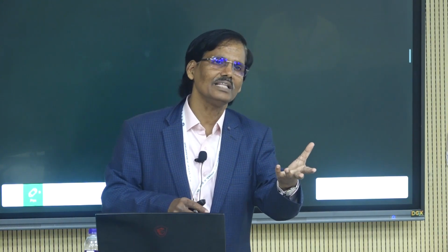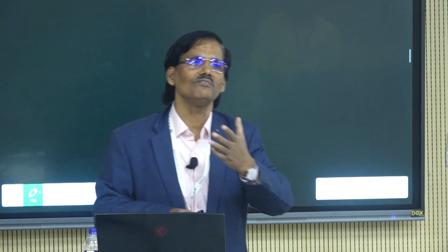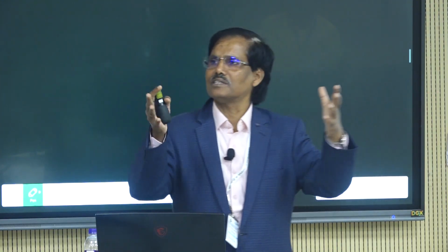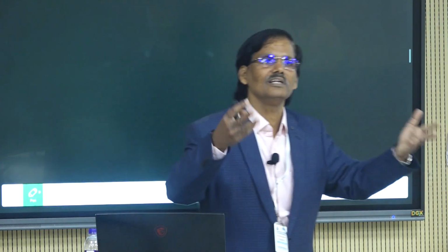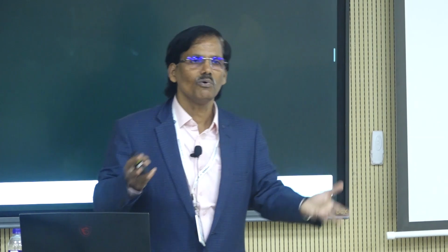about the flow field. The higher the flow strength, the more effectively heat is transferred. When it is quiescent, a little bit stagnant, then the air behaves as an insulator, right? When it is moving, it is carrying over the energy and dumping it on the other side. So that's more effective. So obviously, higher is the Rayleigh number, you will find that if you see the next one.